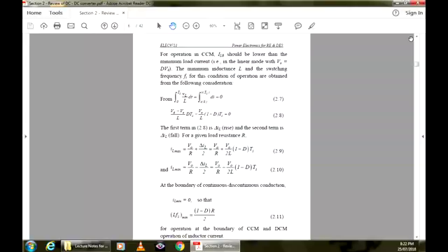If you then say that the minimum current will be 0, which is the case for operation at the boundary, then you set this equal to 0, and you equalize that with that. And then you come up with this expression that L f_s min is given by that. Which means that the switching frequency and the inductor have an intertwined relationship. You can change one, and then the others will be determined accordingly, so that up to a minimum load current, the converter operates with continuous conduction. Normally we would use this formula for a given switching frequency. The inductor value will come from here.